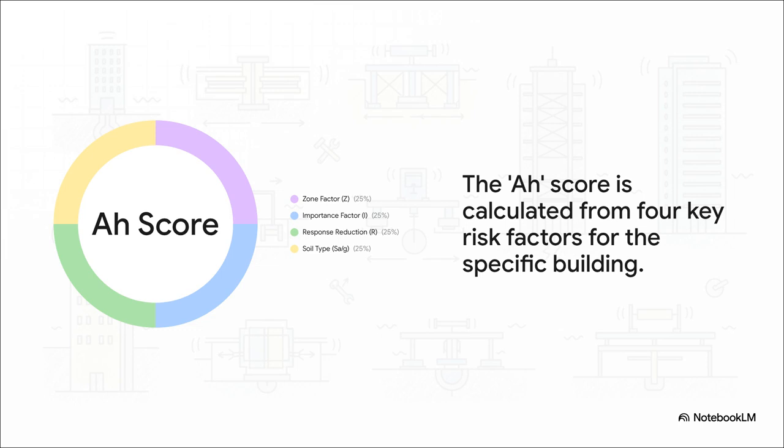First, where is the building? Is it in a high-risk zone? That's the zone factor. Second, how important is this building? A hospital, for example, needs to be way safer than a storage shed.